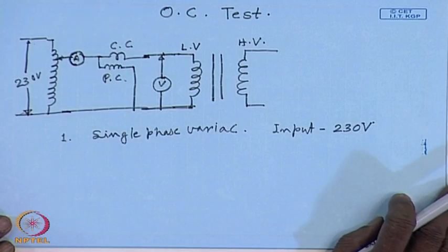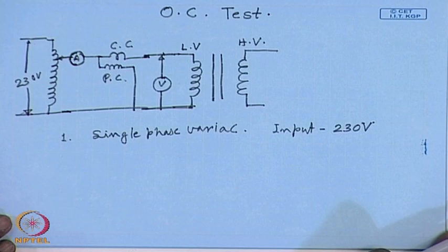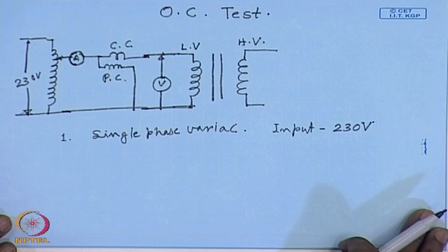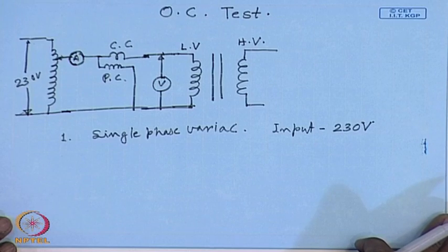from this variac will be the no load current of the transformer, which is very small. On the LV side, the rated current itself is 20 ampere. The no load current of a transformer will be around 5% of that. So, the no load current will be within 1 ampere. So, a variac that can give 1 ampere output current should be sufficient for this test.